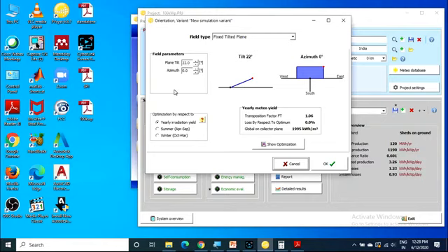For my Warangal location, the latitude is 18 degrees. If you click on 18 degrees, you can find out how much energy is collected by the solar module, and it will be displayed here. So the latitude will give the idea; that is the near optimal value. You can change the angle so that you can find out how much energy is collected by your module. That is about tilt angle.